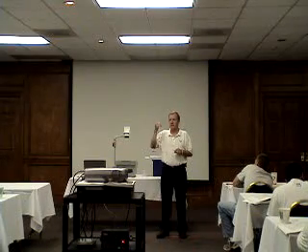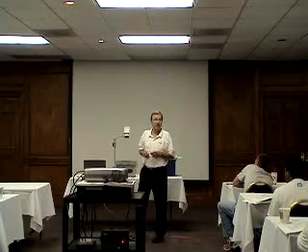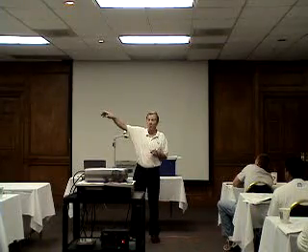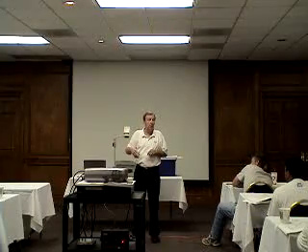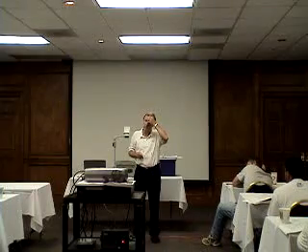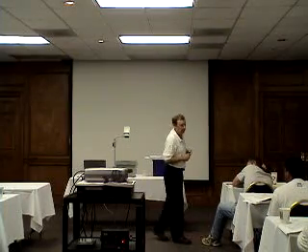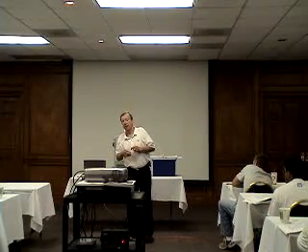Where are we going to get this mix from that we're going to resample and retest? Where's it going to be by the time we know our test result? I told you earlier, it takes about 3 to 4 hours to do a full test series. It's out there already put down. Usually it's already on the road. So you're talking about taking some mix up off the road, and usually that's what occurs. You either cut it out with a core machine or cut it up with saws or something of that nature until you get enough of it cut out and cut up to perform a full test series.